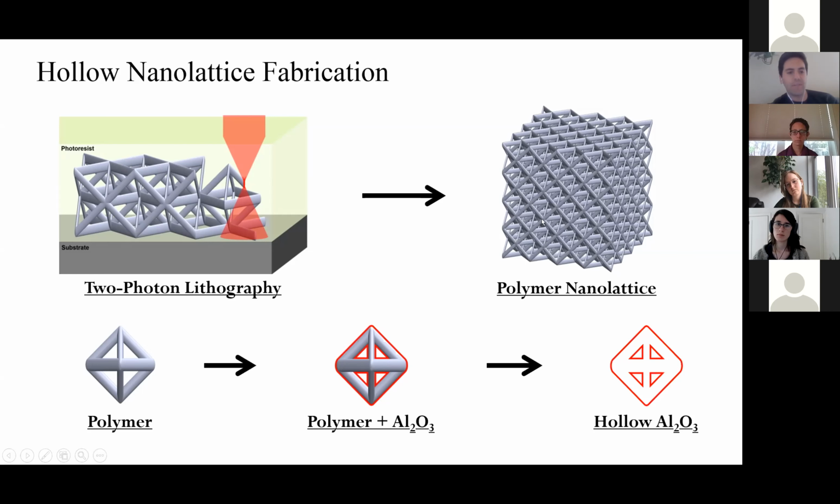So this is kind of a lost wax method or something like that. There's other processes you can combine with these. You can change to pre-ceramic or pre-carbonic photopolymers and use pyrolysis to create a carbon or a silicon oxycarbide structure. You can use sputtering to get metals. You can do this in multiple processing steps to get different coatings of materials, different thicknesses. But I'll leave it at that. There's a whole bunch of variability in the processing techniques we have.